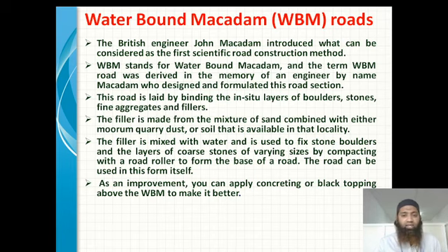How did he do that? You can see here WBM stands for water bound macadam, and the term WBM road was derived in memory of an engineer by name Macadam who designed and formulated this road section. So he was the first one to come up with this unique construction method. This road is laid by binding the in situ layers of boulders, stones, fine aggregates and fillers.